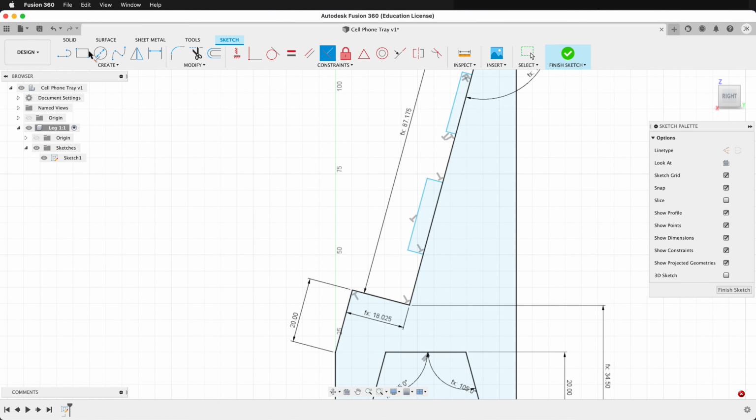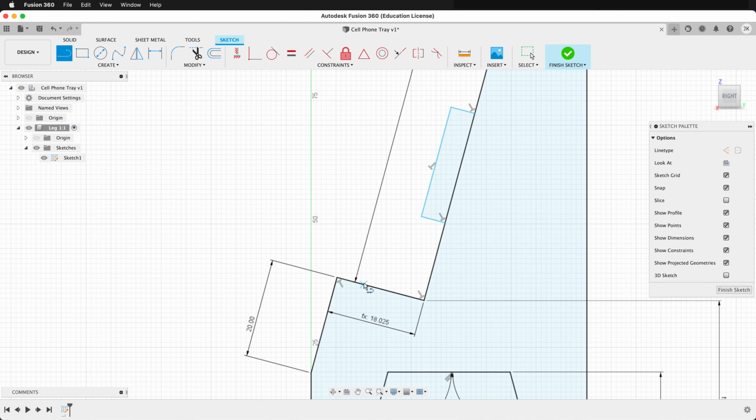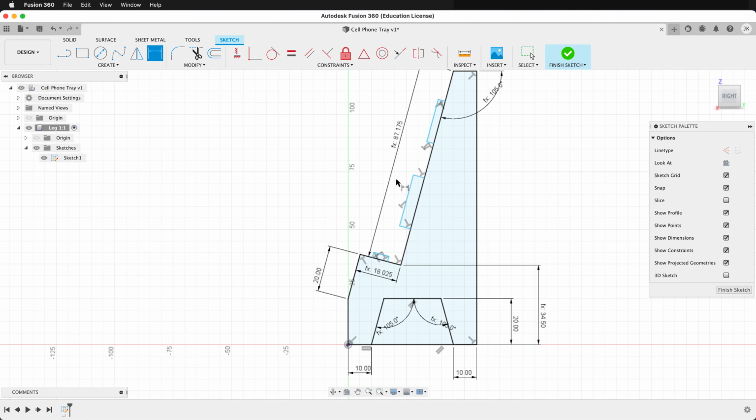And then we're going to draw one more tab. We're going to draw a tab down here. So there's my 90-degree snap, my snap, and my snap. Now our sketch is no longer fully defined. So let's press the D key and start defining it.